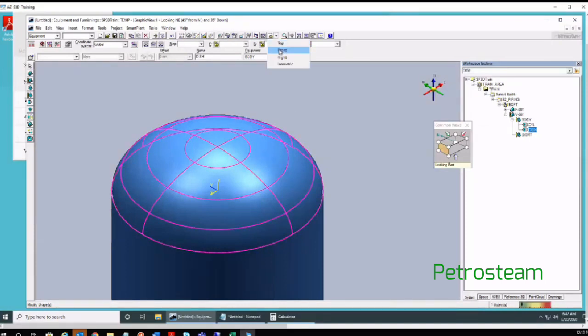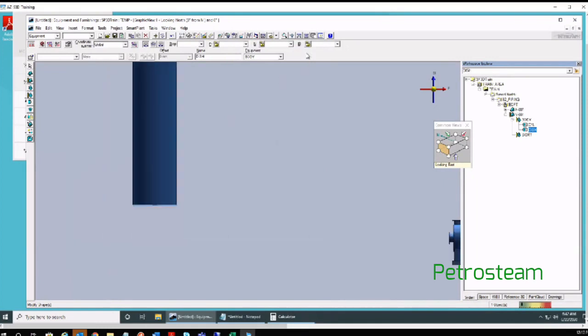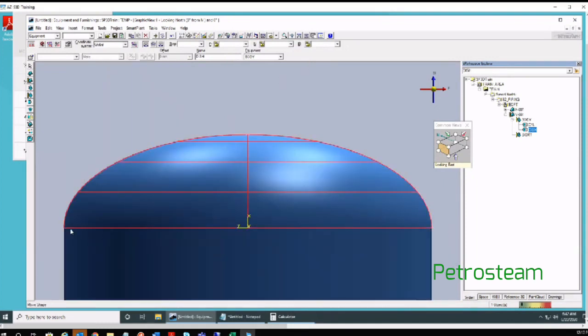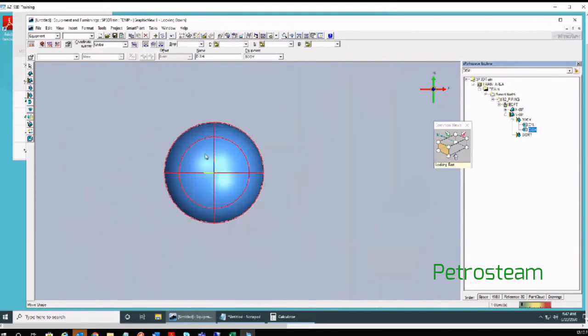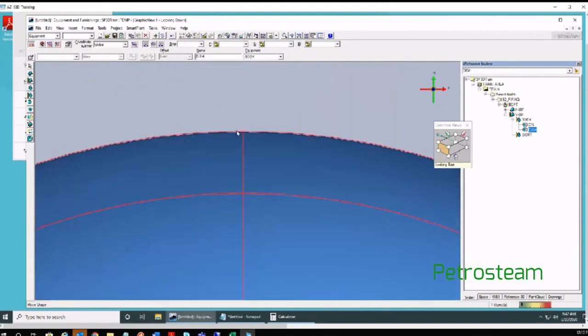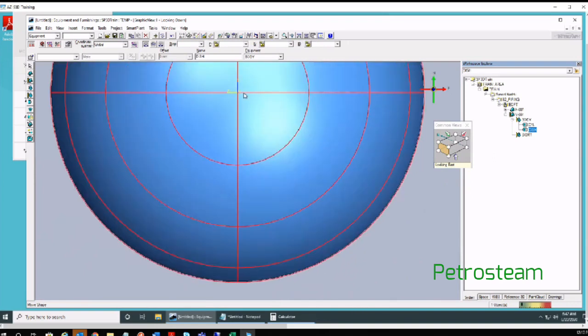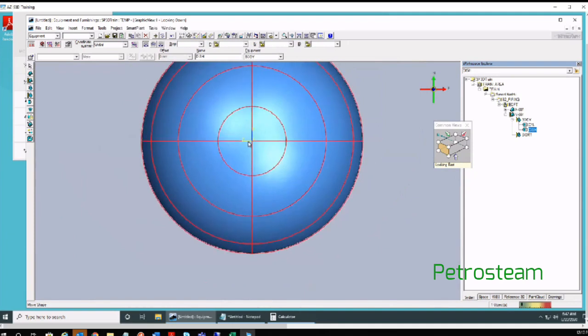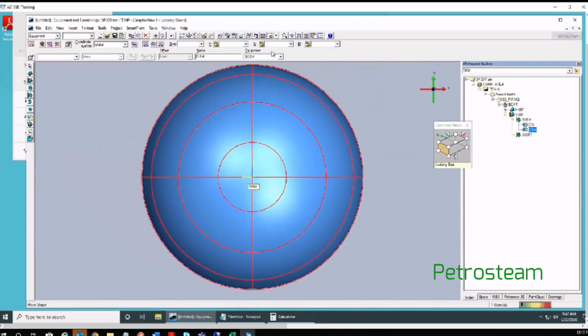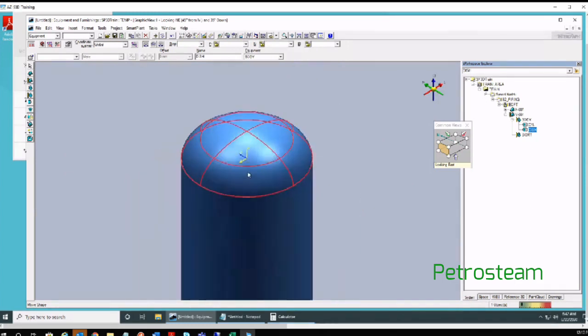You just make sure in front view and top view whether it's coming at the proper location, whether it is coming accurately on the cylinder. Always after placement, you check in different views, because maybe during your cursor selection, sometimes it won't select properly at the required location. At that time, you change views and make sure that it is placed at the right location. Okay.